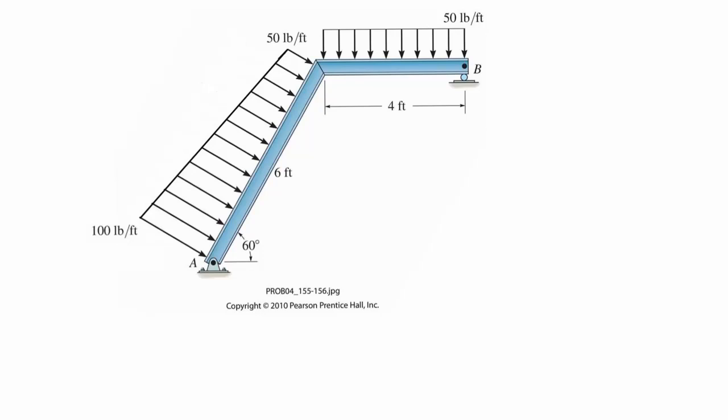The problem doesn't tell us what's causing that pressure, so we just have to take it like it's modeled, and say that the pressure is coming from that direction, and that's the way the resultant force would also be modeled. So let's go ahead and model these as two pieces. And we know a little bit about how to do this now. There's the centroid of the triangle-shaped load. We'll call that R1, and this will be the centroid of the rectangular load, and we'll call this R2.